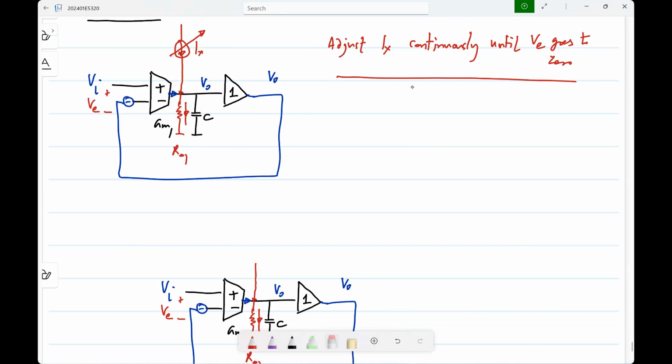So now first we want to make a variable current source. What's a reasonable way to do this? I mean, an electrically variable current source. MOS, yeah. It's a voltage controlled current source, like one more GM, that's all, right? So now I'll have this, and if I vary this voltage, so this is some sort of control, the current will vary. And what is it that I want?